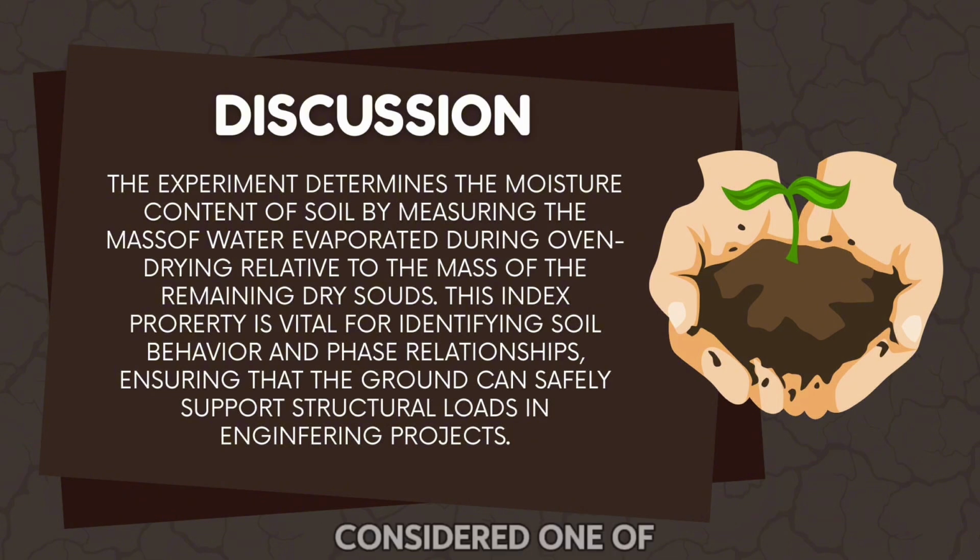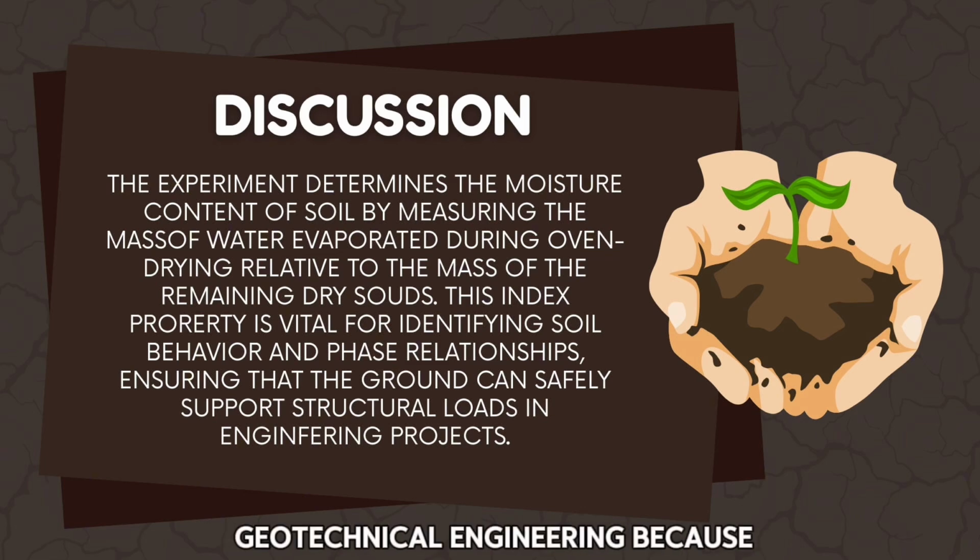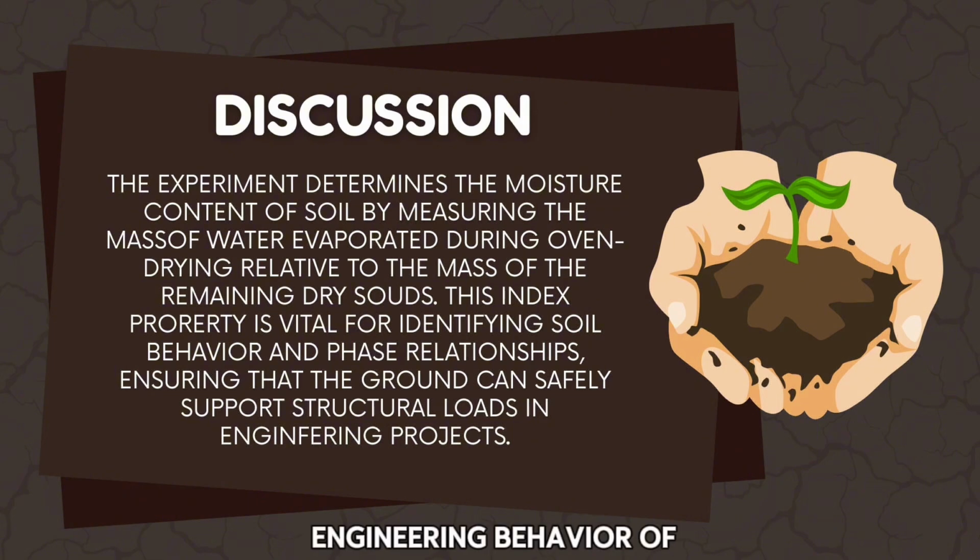Moisture content is considered one of the most important index properties in geotechnical engineering because it greatly influences the physical and engineering behavior of soils, including strength, compressibility, permeability, and consistency. Moisture content is highly sensitive to environmental conditions, which is why proper handling and storage of soil samples before testing is important.